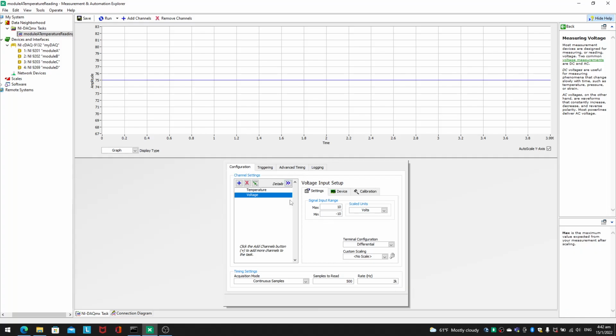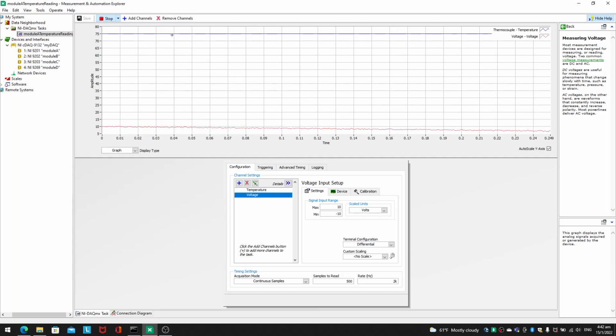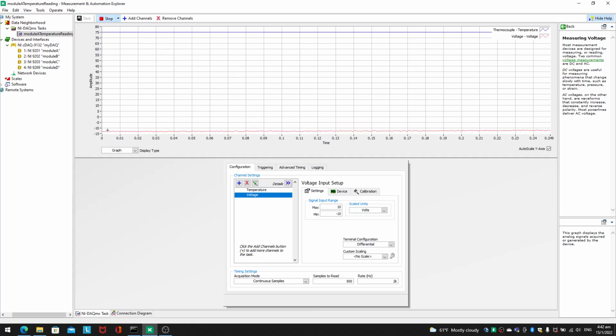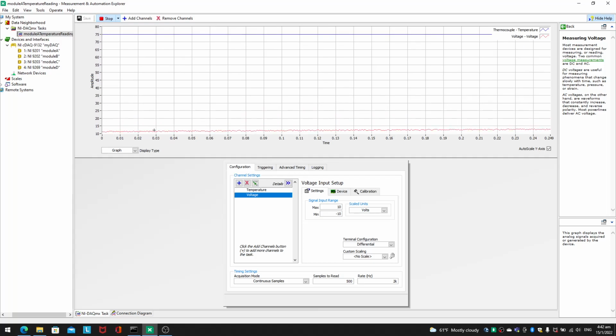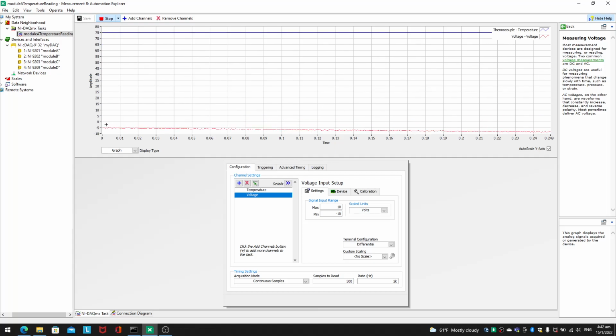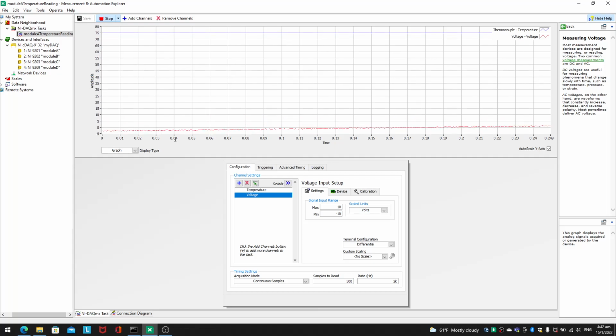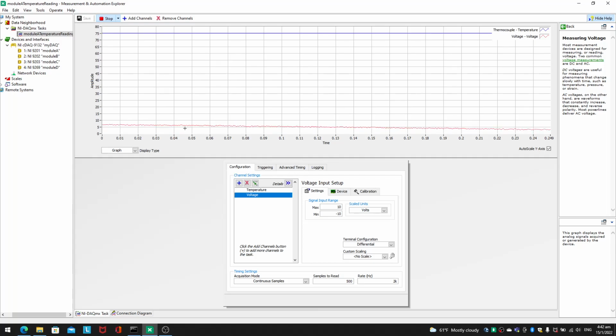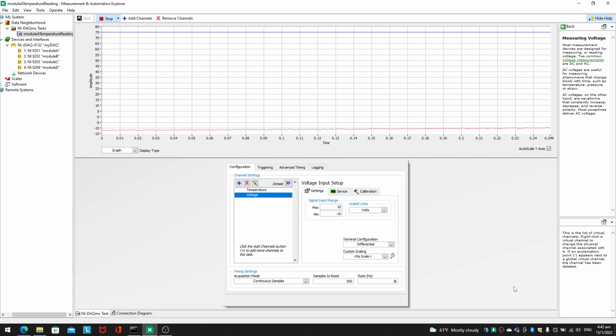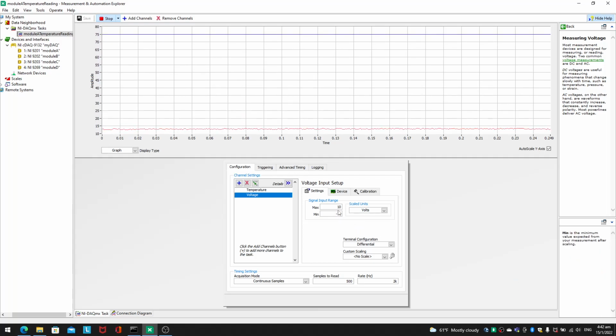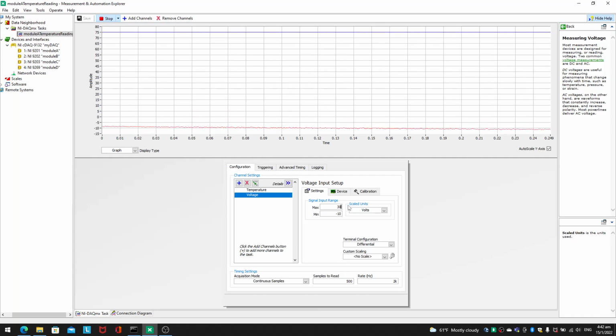So voltage, normally what you'll see is a sine wave output. Scaled units is in volts. Then I can just click run. So you will see two things down here. One is an alternating, I guess AC, voltage going up and down between -10 and 10, which you can play here. You can change this to 30 if you want.